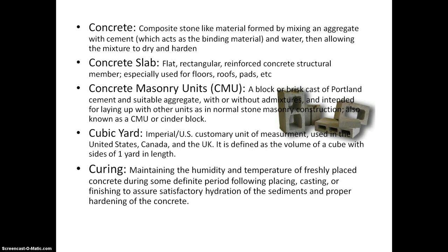Curing is maintaining the humidity and temperature of freshly placed concrete during some definite period following placing, casting, or finishing to assure satisfactory hydration of the sediments and proper hardening of the concrete. It's basically after you pour it all and you let it set, and you want to make sure the humidity and temperature is right so it can gain the proper strength for when it's dry.